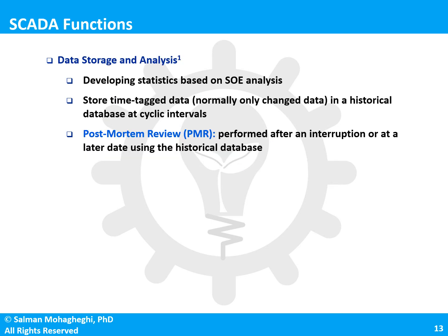The SCADA system also has the capability for data storage and analysis. As I mentioned earlier, this is quite important for sequence of event analysis, especially because all the data points are time-stamped. You can always go back and see what root causes led to a particular disturbance or a particular outage. What is known as the post-mortem review or post-mortem analysis. You can store this historical data and go back to it, not just for post-mortem analysis, but you can do all sorts of statistical analysis using the historical data that you have, and the SCADA system gives you that opportunity.